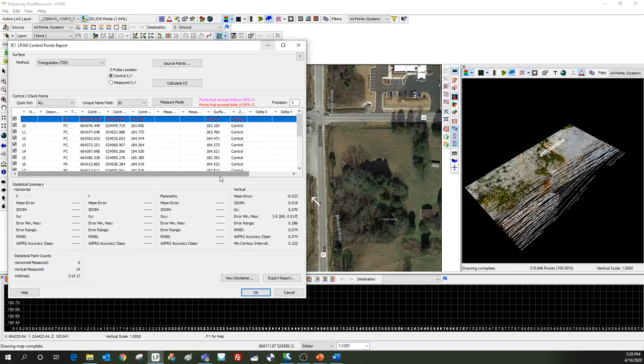Now just keep in mind we want to make sure we're using valid points for this comparison. So you want to make sure your points are on a clean level surface or location on your project. So definitely don't want to have control points or checkpoints in grassy areas or on slopes. Definitely not next to tall buildings or vehicles. Just make sure they're nice open flat areas.